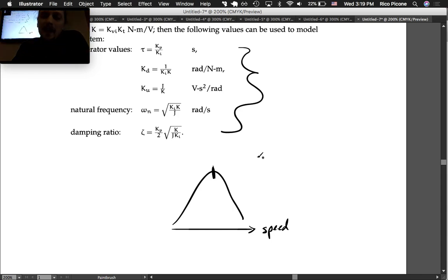But yeah, on one end you're losing, so when you're up here and when you're going fast, your voltage is high, your current is low in steady state. This is always a steady state curve. And then speed is really high though, so the speed's high. So your damping is the dominant loss that happens. Down here, your speed is low, so damping is low, right? So you don't have much damping loss, but you have high current at low speed. So you have a lot of electrical losses.